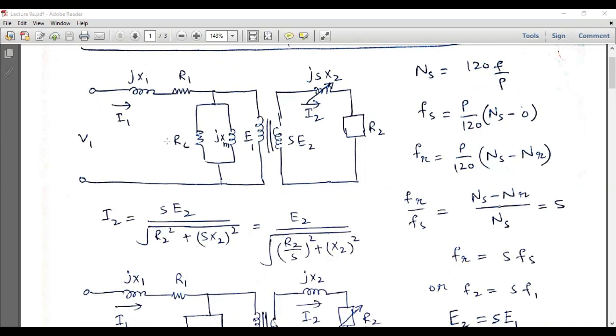And the reason behind this constant and revolving magnetic field is that the three-phase windings across the stator of an induction motor are lying at some angle, for example, 120 degrees for the case of three-phase and 90 degrees for the case of two-phase AC supply. So in this case, the net magnetic field will be constant, but it will be revolving at the synchronous speed.